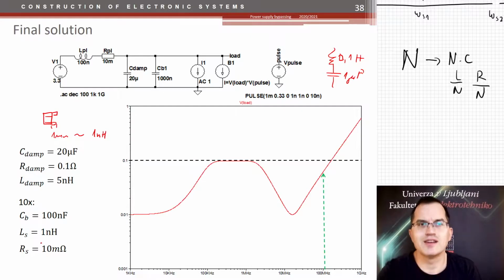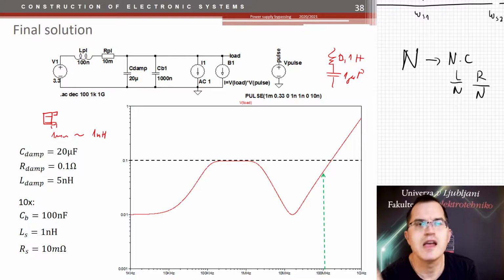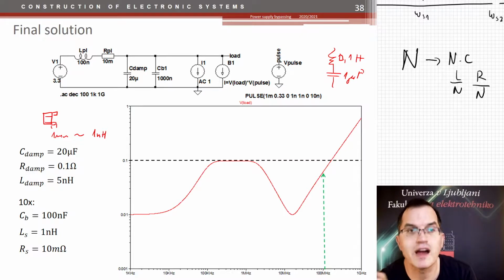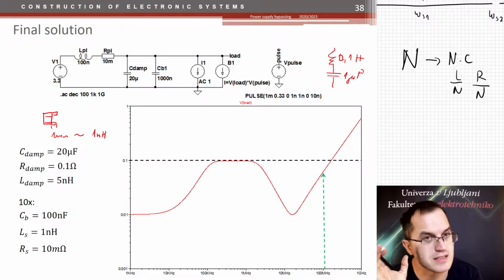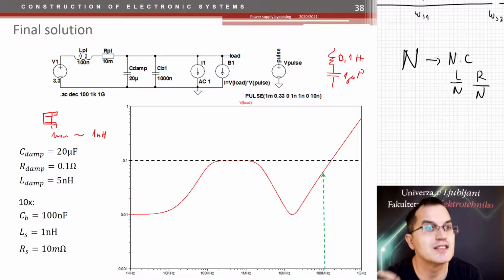So even if I have such a capacitor, I cannot connect it, because every track that I will use to connect it would give me more inductance than I need. Therefore, I need several of them. And several of these capacitors can be placed if my integrated circuit has several power supply connection lines, power supply pins.